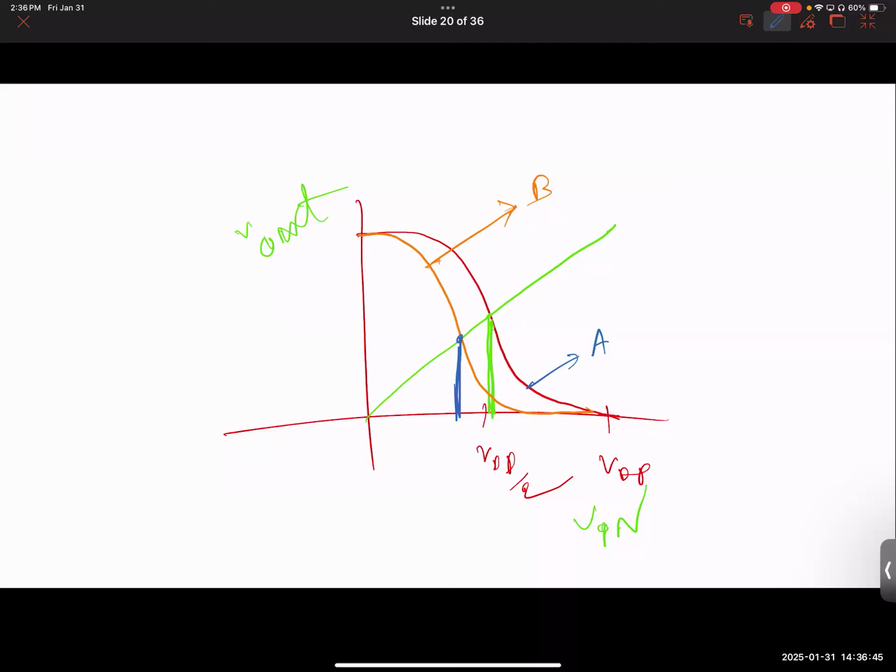Great. Yes. Thank you. That's definitely one. There are other ways as well, but that's probably the easiest one to do. You can always make the transistor sizes asymmetric. Maybe make the PMOS bigger, NMOS smaller, or vice versa. But can you tell me, what was done here? Whose size was changed? NMOS or PMOS? And when I say changed, what kind of change? Did I increase the size of the NMOS? Did I decrease the size of the NMOS? Is there any way to figure this out logically without memorizing or going through the book?